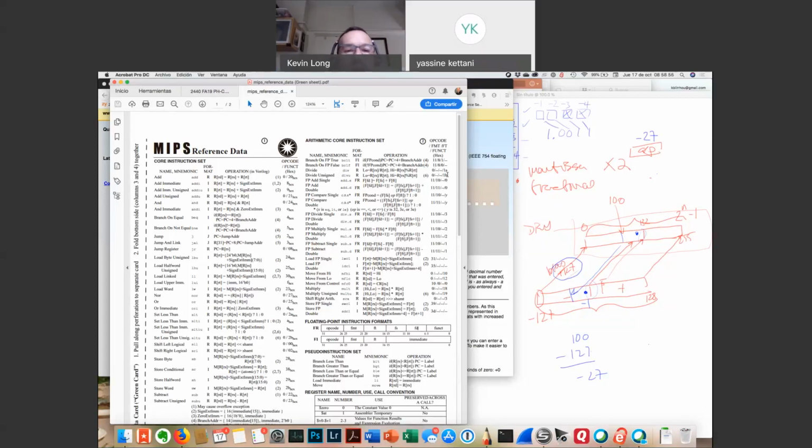So you do still have some mathematic ones here like divide unsigned, which are R-type, and they have 0 for the opcode and a 1B for the function code. What's different over here is they've given us a couple of other fields to represent something called format and FT, FMT and FT, in other words. These FR and FI ones that we were just looking at, like here's an FR one, floating point add single precision.